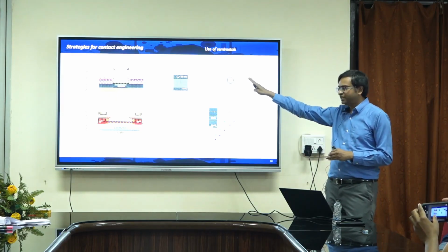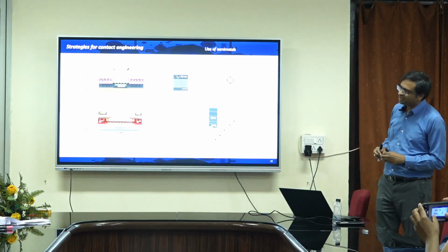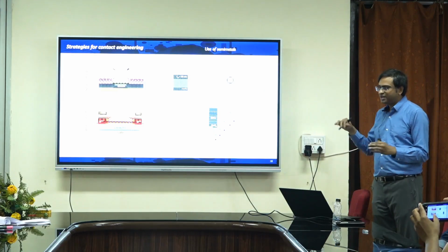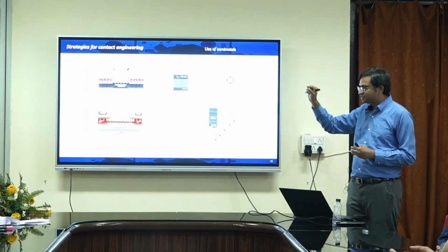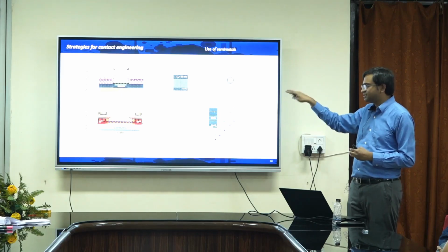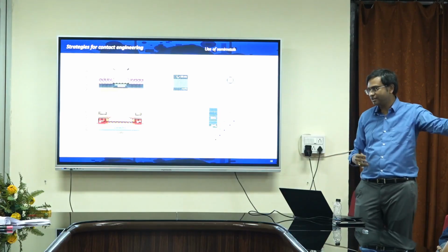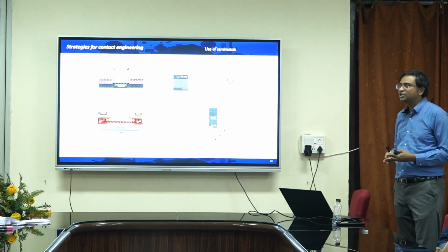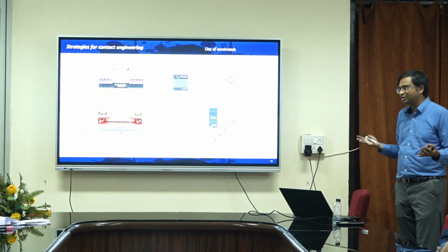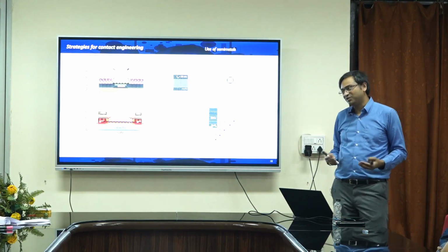You could literally use even nickel, titanium, anything as a capping layer. It is all based on your particular need and how good your probe station is. As long as your contact is more than 3 to 5 nanometers, that's your contact. The gold does not influence your contact because it's too far, as we saw. It does not impact anything. So you can cap it with whatever is available in your evaporator. Most often than not, it is all about what you have in your evaporators, and you put that metal and what works for you.